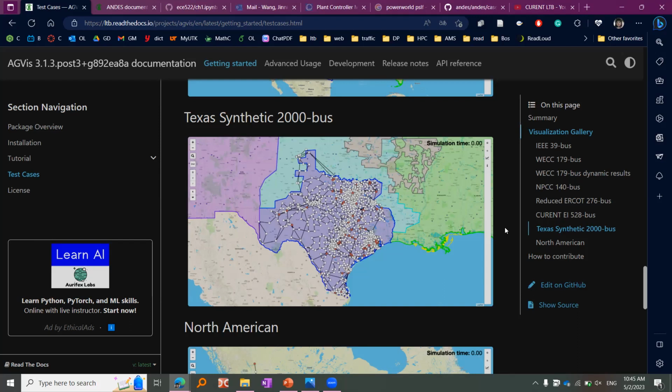There are clearly certain phenomena that you won't be able to see in something like this, like inverters. If they're weakly connected to a grid, they tend to have something called, you've heard of it before, resonance phenomena. Essentially, they'll be resonating against the system. You cannot see that if you use the types of models that are in ANDES and the LTB. You have to have some actual hardware to see it.